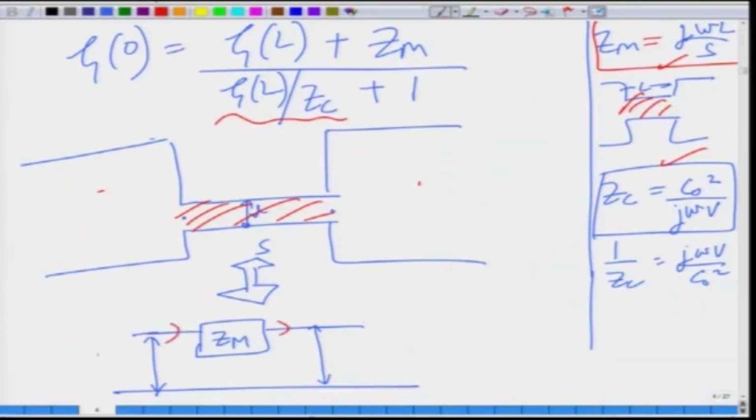So this is the electric or the acoustic velocity, or the current, and this is zeta at x equal to 0 and zeta at x equal to L. Clearly, whatever impedance we are seeing at these two points and whatever we are seeing here are related by the relation I just wrote down. The same continues on the next page. For a tube sandwiched between two large cavities, we just need to find the inertance at very low frequency, and this is the electroacoustic circuit for that.